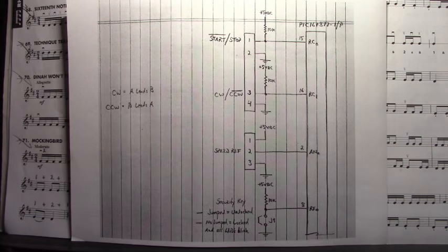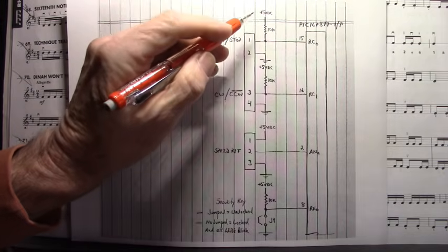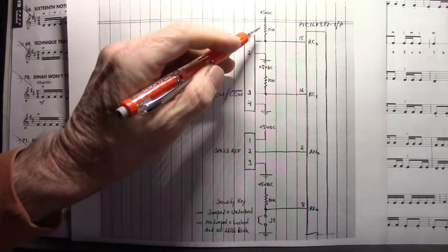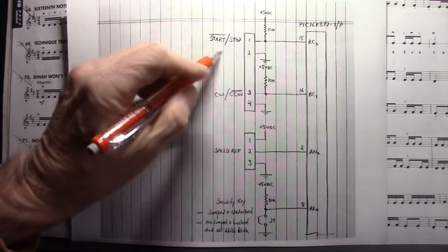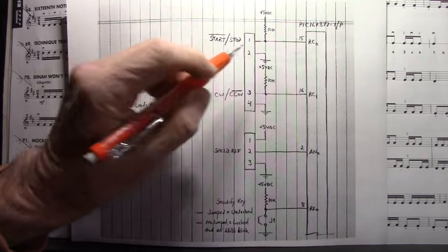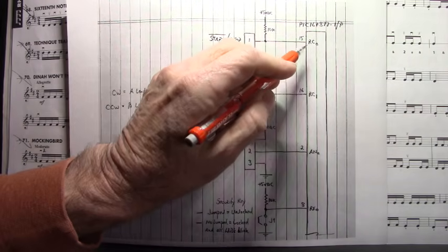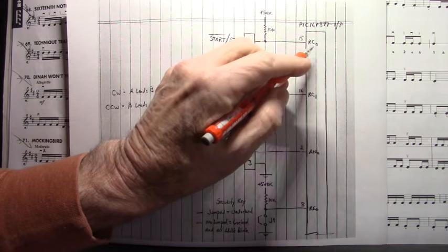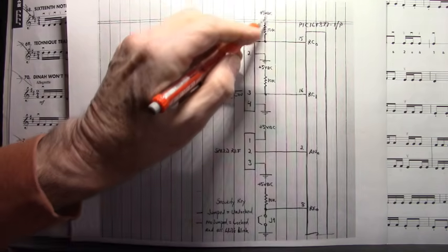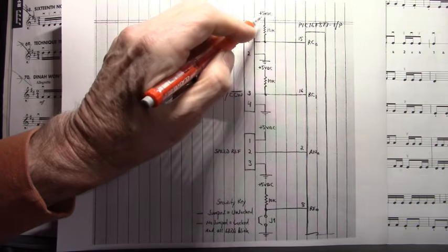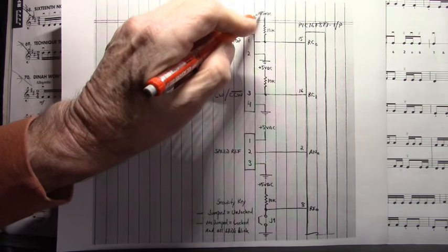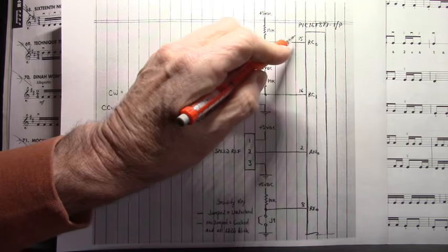But remember the inversion, because an optocoupler will invert the input from the opposite state of what you wish. So what I'm saying is that here we have 5 volts applied. This is when this circuitry is open. You have 5 volts applied to port C0 through this 10 kilo ohm pull-up resistor pulled up to 5 volts, so you have a logic 1 right there.